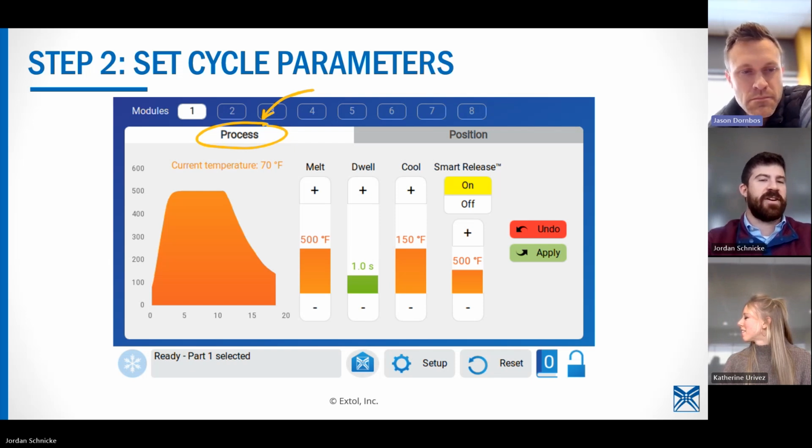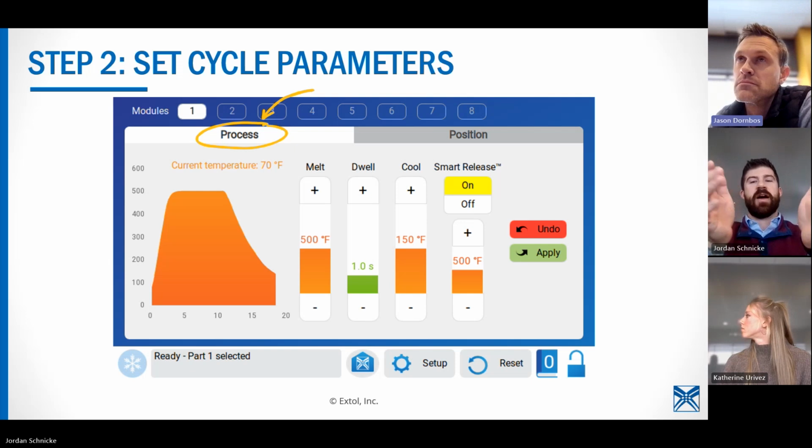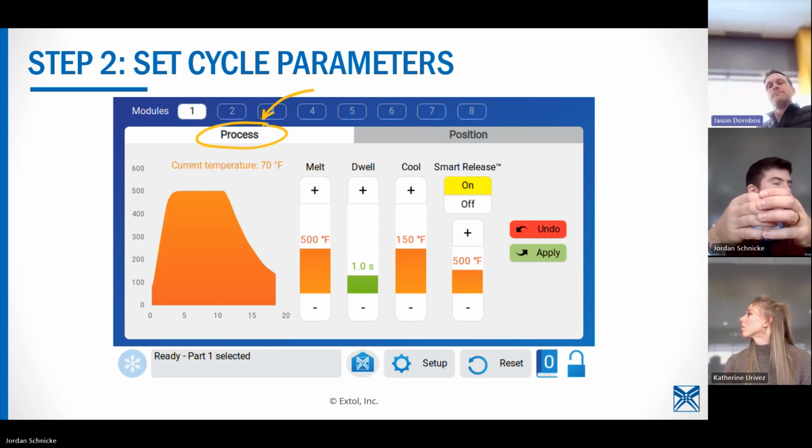Yeah, sometimes. What I see happen more often than not is if something's misaligned or if the mold doesn't perfectly match the CAD, you get a little bit of flash somewhere. More often than not, I see the flash actually wraps around the forming tool, the NanoSTAKE, and when you cool it down, what happens when things cool? They shrink. They kind of bite on the tip. So if you heat it back up and apply a little bit of pressure to retract it, generally it helps